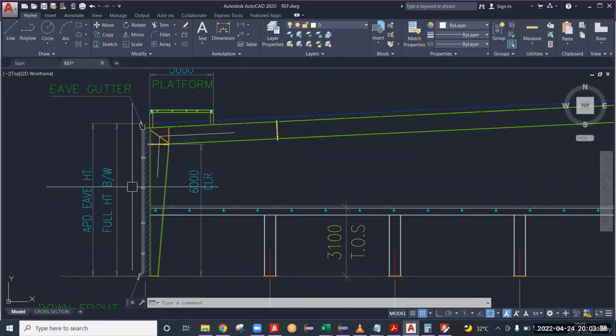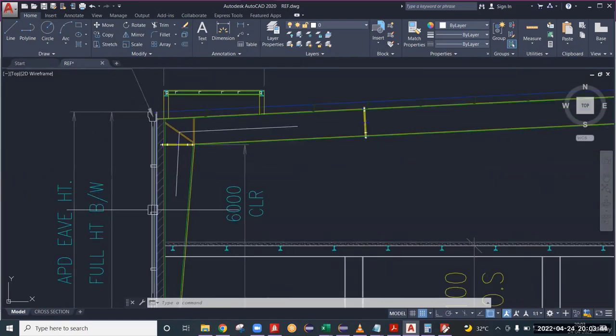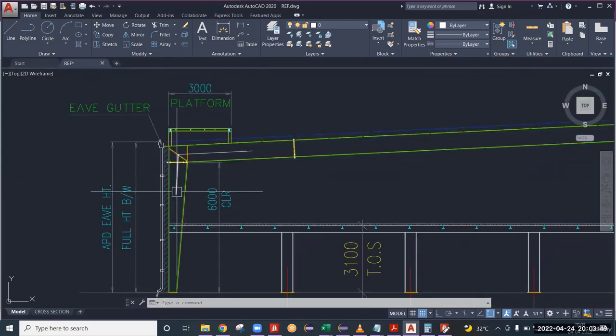But in this case, if you have girts, say a 3 meter block wall and sheeting above, there will be some secondary members to support the sidewall sheeting, which we can call girts. Those girts will provide some sort of support to the column.